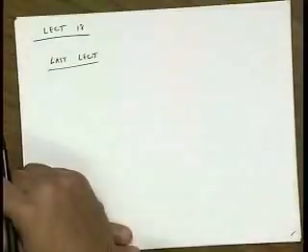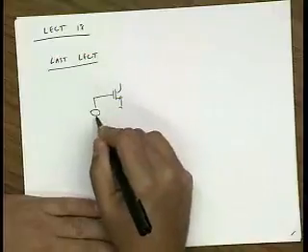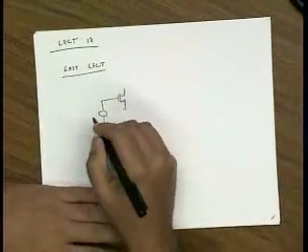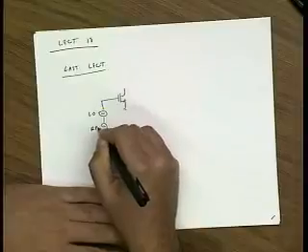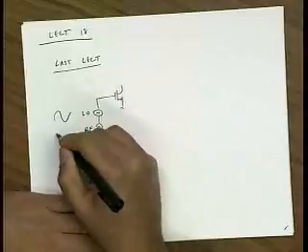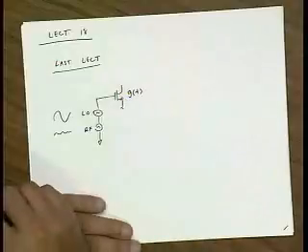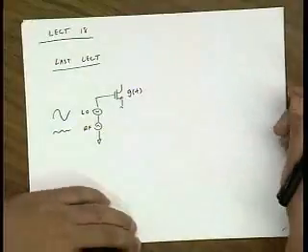Okay, so let's go back and look where we left off last lecture. Now, we covered a lot of ground last lecture. Basically, we talked about mixers where we vary the transconductance of a device periodically. For instance, a mixer that maybe looks something like this, where we have an LO and an RF riding on top of each other, and the LO is a large signal and the RF is a small signal, and the LO creates a time-varying transconductance. Okay, and that gives us a mixer.